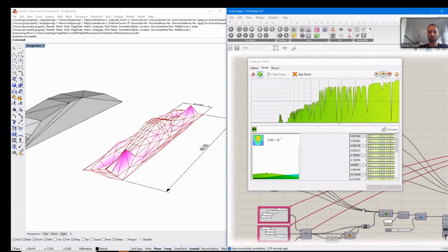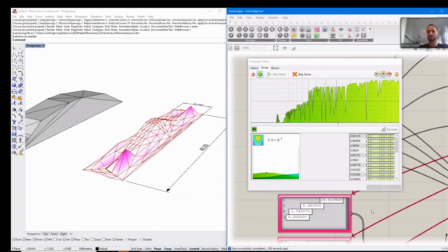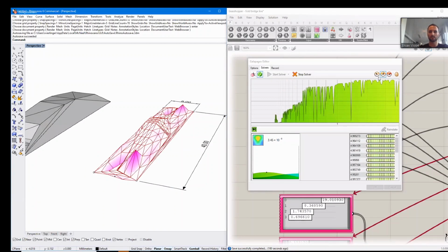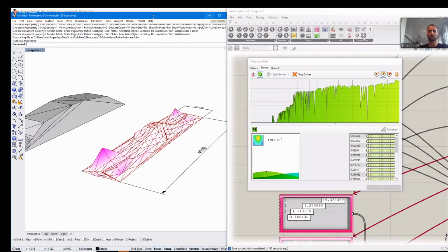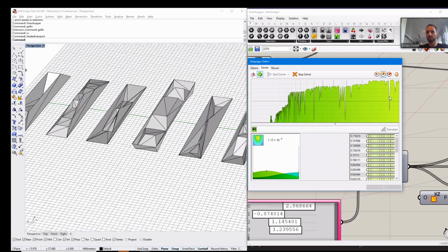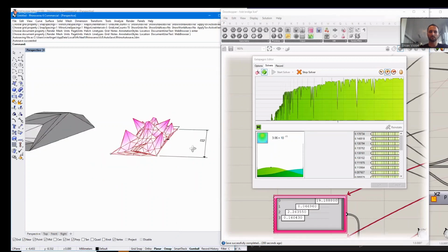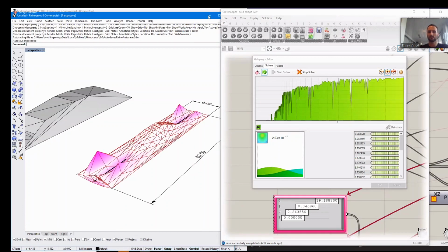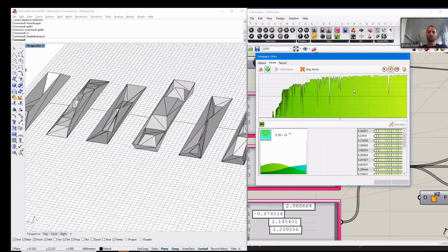So it's working hard. What we can do to speed up the process quite dramatically actually is to minimize the Rhino and Grasshopper main windows, because you see here it updates for the solutions, it updates the user interface and also the Rhino viewport sometimes at least, depending on the setting here. And this takes quite a lot of time. So if I click minimize in the Rhino window, you see immediately that this progress bar here speeds up quite a bit. So if you're not really interested anymore in what exactly is going on in the optimization setup, then you can just minimize that and let it run a lot faster.